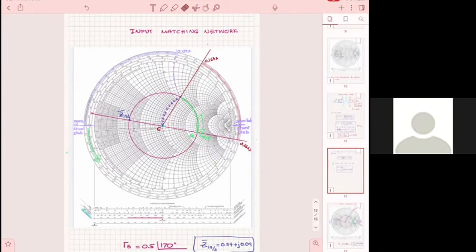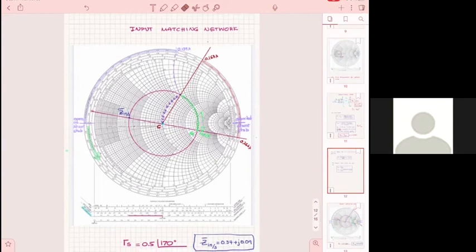Yes, it's wrong, because you have to start at the point where you get the reactance. The point B here, and all the points on this circle have the same reactance. And the reactance is here, this value.